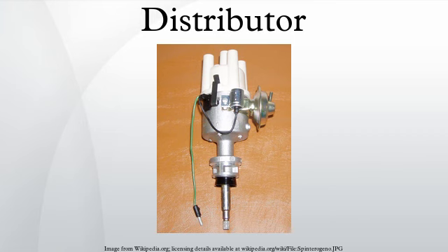Direct and distributorless ignition. Modern engine designs have abandoned the high-voltage distributor and coil, instead performing the distribution function in the primary circuit electronically and applying the primary pulse to individual coils for each spark plug, or one coil for each pair of companion cylinders in an engine.